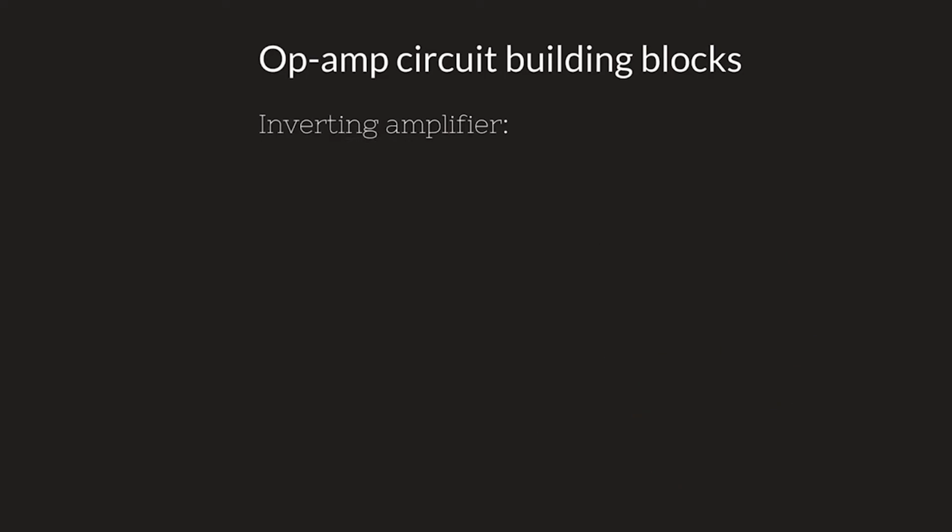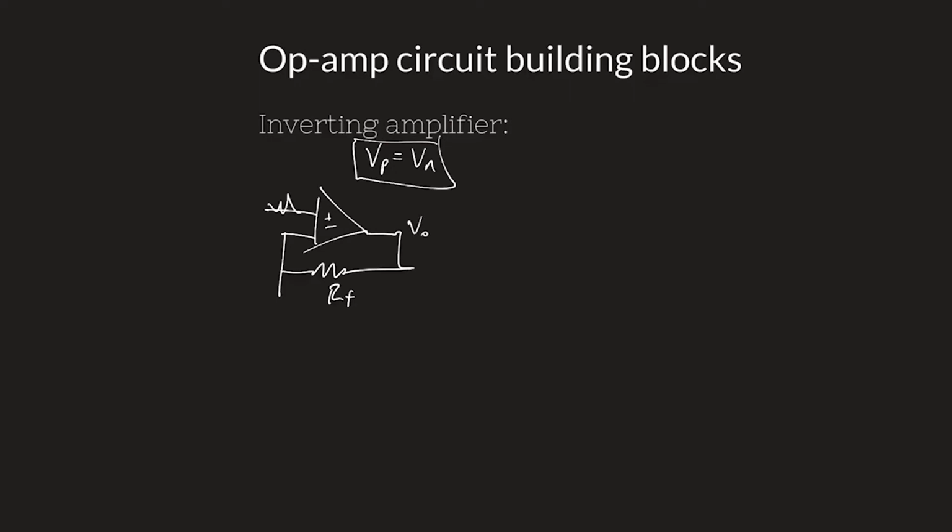So now the inverting amplifier. It's always going to have negative feedback. That's what stabilizes it so that we can say Vp equals Vn. That's always the case for negative feedback. In is equal to 0 for all the op amps. That's the ideal circumstance that we have to consider to solve these circuits. Here's VP, here's VN.